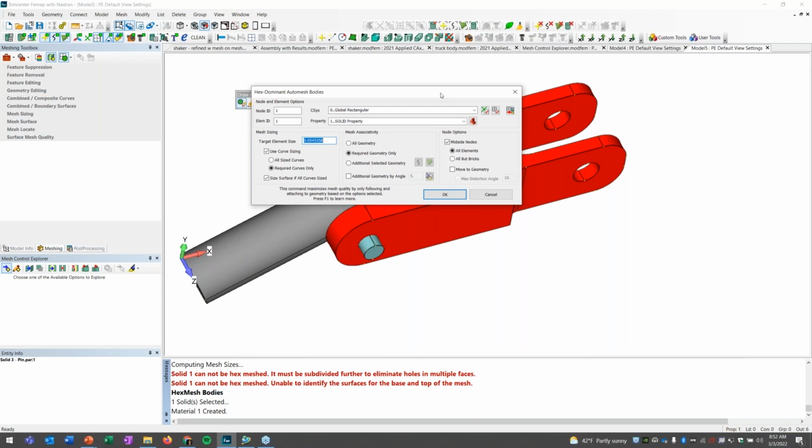It's going to drift from curves or points, and it's not going to be such a hard point there for all of those, because it's going to really try to work for an ideal mesh quality. And it's going to use a target mesh size, not a fixed mesh size, but a general target that you're working towards. So I think it's really just worth opening up some example models, playing around with it, comparing the two methods, and seeing how the two differ, because it really is a new approach.